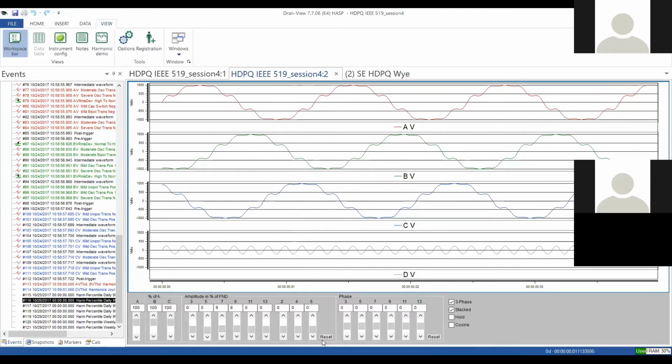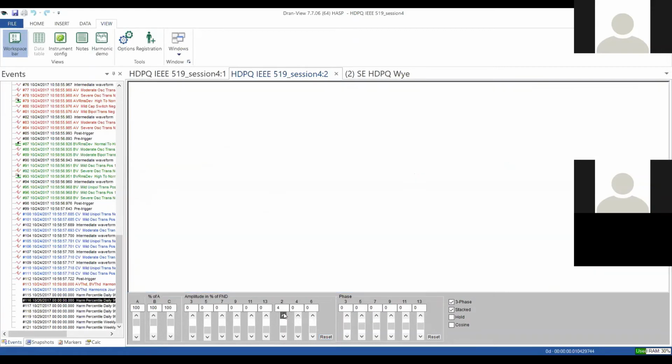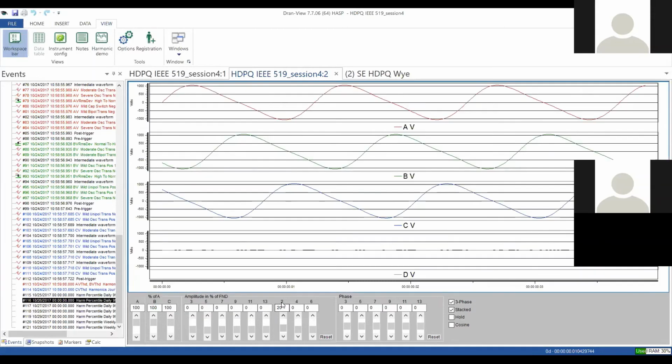Okay. We're going to talk about even harmonics later, okay? Many people think that even harmonics cannot be triplet harmonics. Well, mathematically, yes, they can, but as we're going to speak about in a couple slides, they don't appear as often in power systems. So as an example, if I put in the second harmonic, I can do that. All right, you can see, look how distorted. This is like a slope here. This is not an AC waveform anymore, okay?